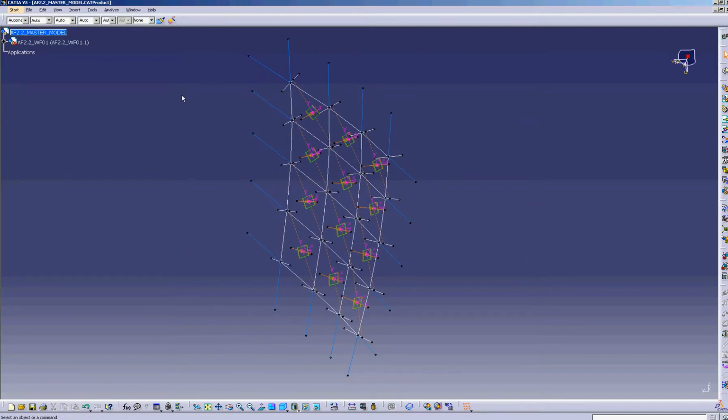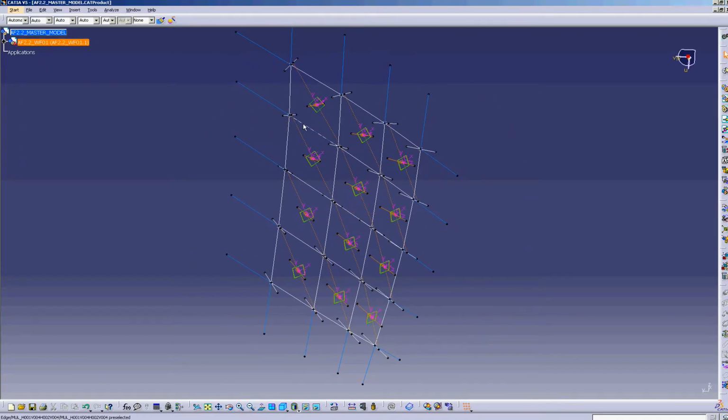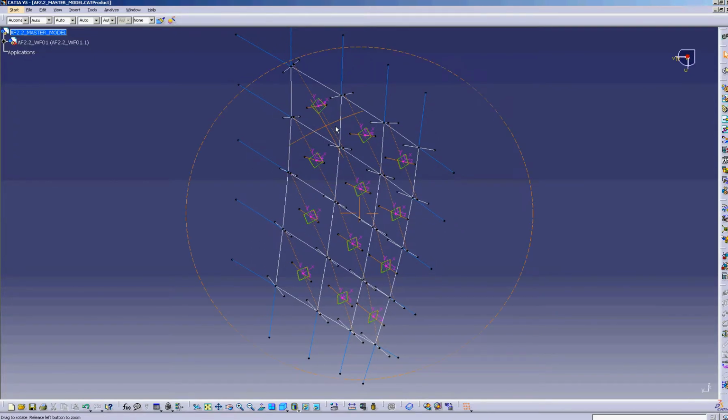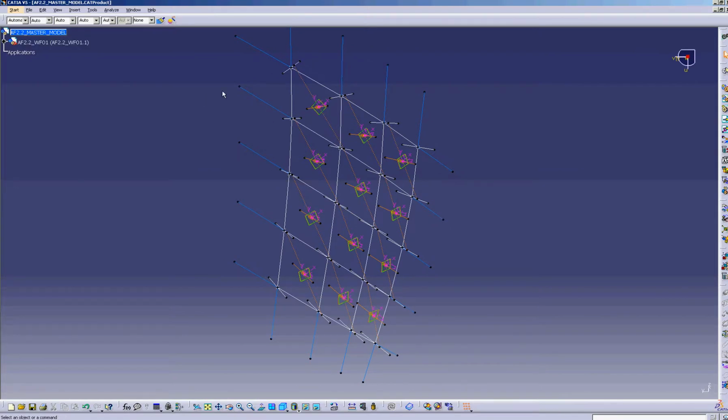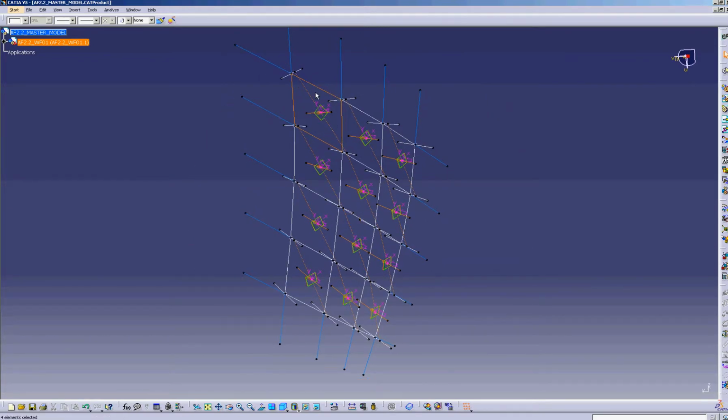The next thing that we're going to want to do is we're going to build up geometry for an individual panel in this facade. So as I said earlier, this wireframe is built up with a number of divisions. I guess we have 12 different panels here. And what we're going to do is we're going to make a parametric prefabricated panel assembly for one unit. And the end goal is to have that unit all built up with all of its solids and all of its parametric behavior and all of its detailing, and make a reusable template out of that that we can instantiate